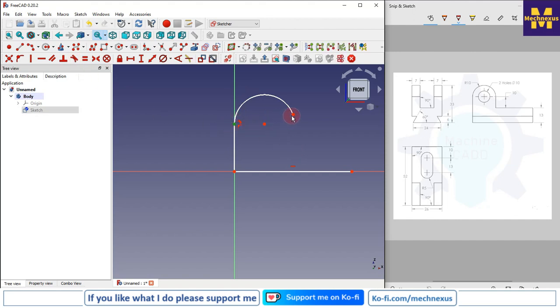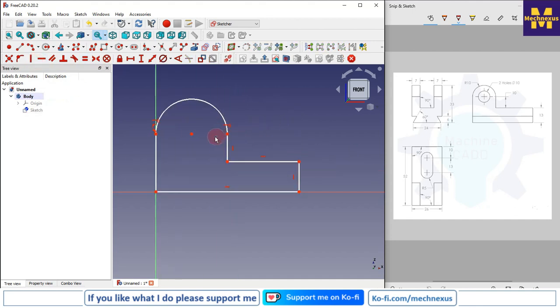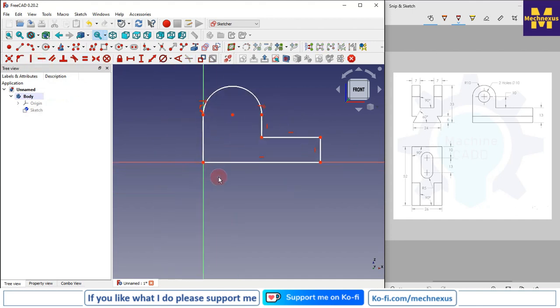and this point set to the horizontal. And now I will draw again one line tangent to this arc, and then I will close my profile and I will make this line vertical. And now we will give the dimensions.